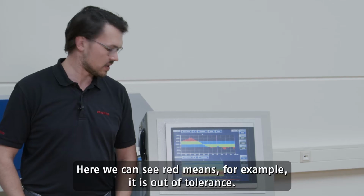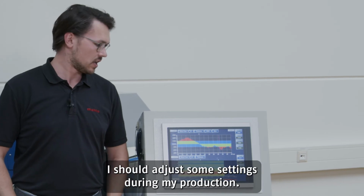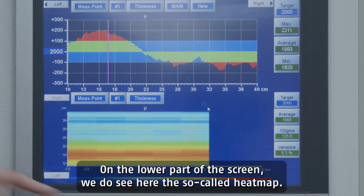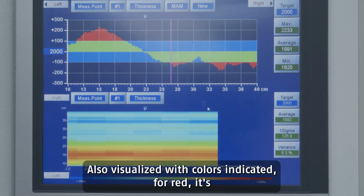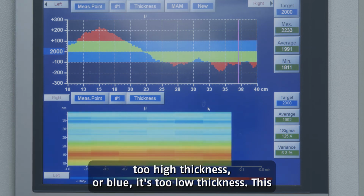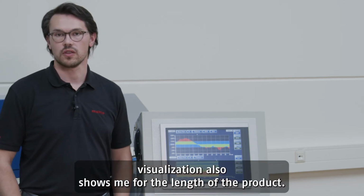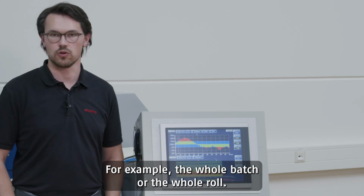Here we can see red means, for example, it is out of tolerance. I should adjust some settings during my production. On the lower part of the screen, we do see the so-called heat map, also visualized with colors. Red is too high thickness, and blue is too low thickness. This visualization also shows me the length of the product, for example, the whole batch or the whole roll.